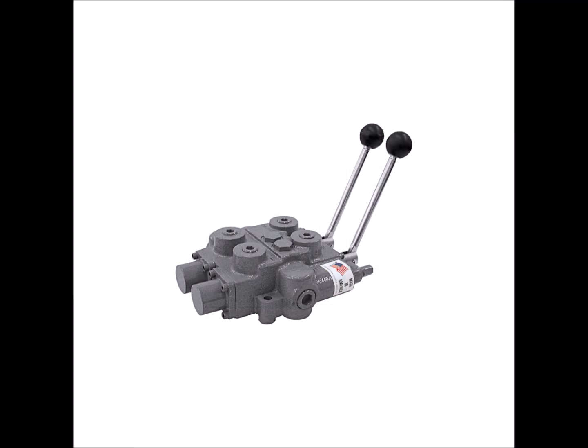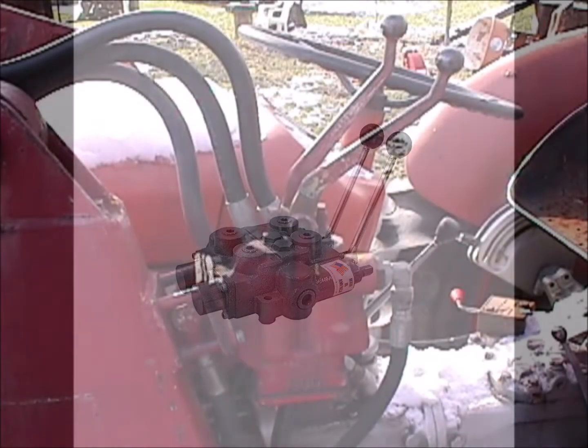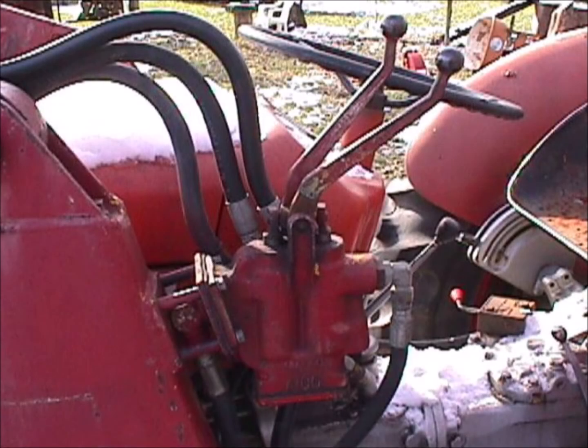You see these things on tractors and other devices where, when you pull the lever, that actually pushes the cartridge back and forth and determines which way the fluid flows. This particular example is usually for raising and lowering the loader and tipping the bucket. If we go ahead now to a real tractor on a farm, you can see here the same type of levers. Again, one to raise and lower, and the metal cartridge you see there is where this slider is going inside, and the hoses simply take the hydraulic fluid to and from that directional valve.